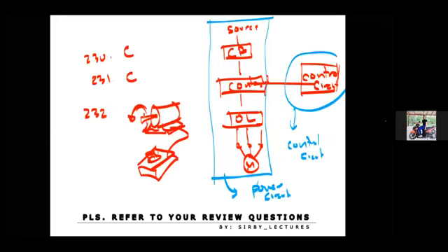When I press this button and hold it for a long time, it will just continue to rotate. But if I don't press it anymore, then this one will stop. So that term is what we call jogging. This is letter A.